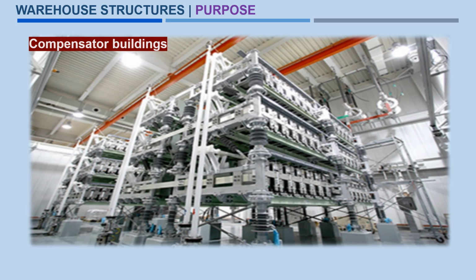Also there will be a maintenance crane required inside, a pump room also required, and some cooling system to be prepared for this. For that, the cooling duct vent needs to be considered while doing the design. Also the crane movement we need to treat as moving loads, and the structural cladding should be thermal resistant or thermally insulated cladding.